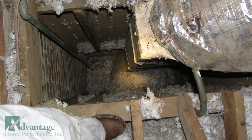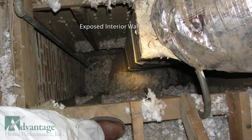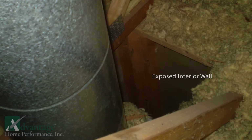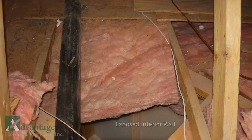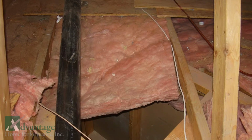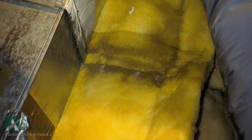Another common defect our auditors locate is open chases that are the sites of significant air leakage and heat transfer. We find these problems around chimneys, drop soffits, plumbing penetrations, etc. Fiberglass bats don't work as a thermal barrier when installed over chases and drop soffits. The last building defect I have time to introduce is duct leakage.